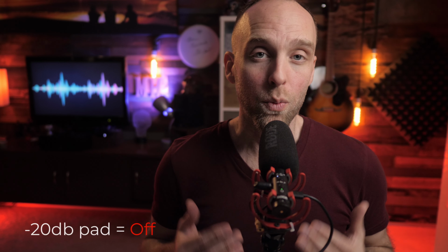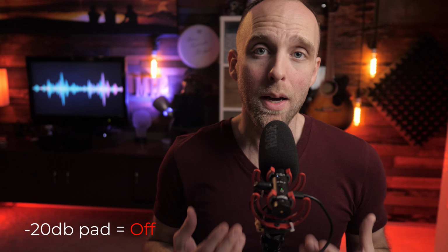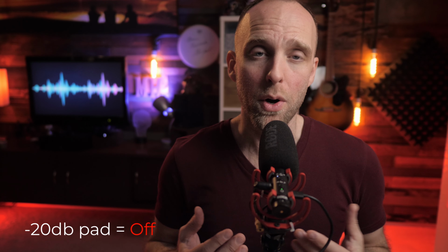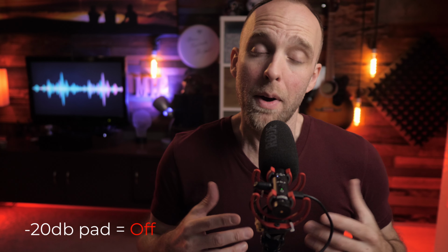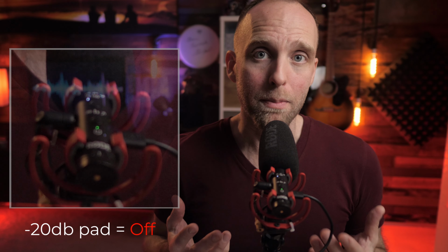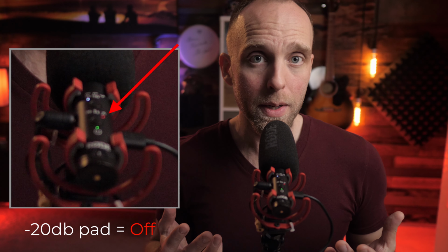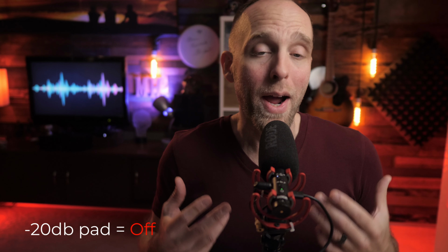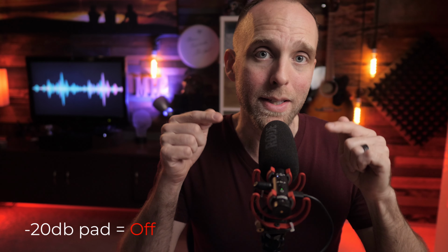Now, real quick, let's put the mic down here closer to me and do the same thing. All right, so now with the mic right here by my voice, the main sound source, my voice is pushing more SPL, or more sound pressure level, on the microphone's diaphragm. My voice is louder to the mic. And if I talk reasonably, I may not clip out the mic, but if I just raise my voice a little bit, you can see, and I can see on the clip indicator on the mic, that when I speak just a bit louder, or if I get a little exuberant, that now I am clipping out the microphone itself.